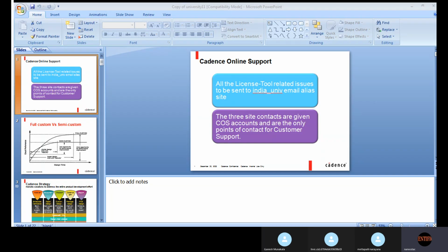All these things I am designing. To design an AND gate also, I am starting from the transistors. With the transistors I am designing the AND gate, and with these AND gates I am designing the adder circuit, and so on. If I am starting from a single transistor and taking care of everything, then it is called full custom design.